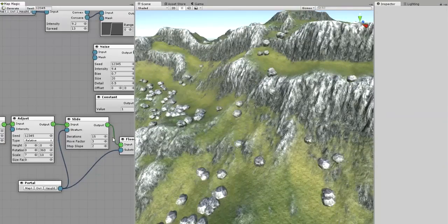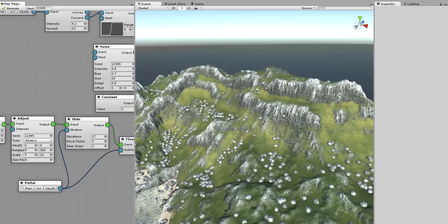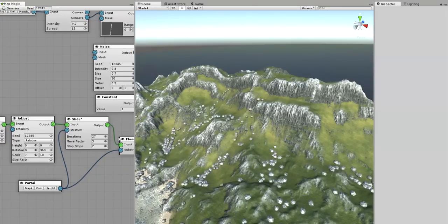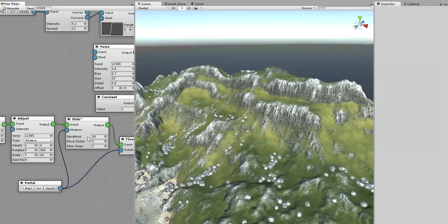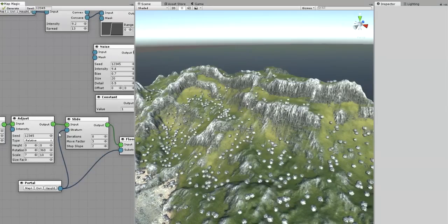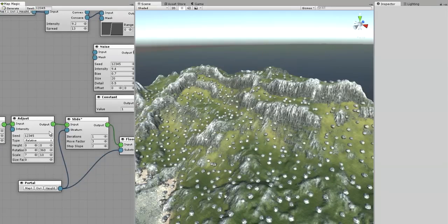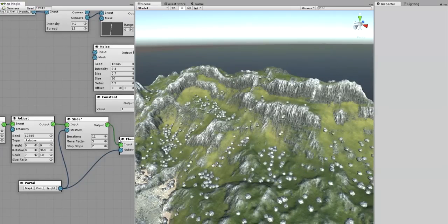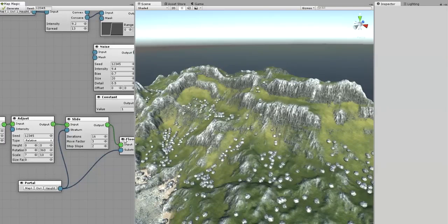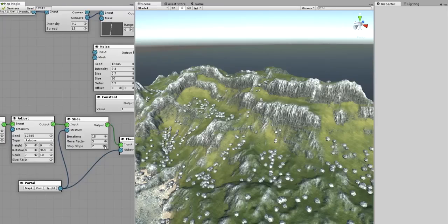Let me increase the number of the iterations and see the whole picture. You can see that the stones are sliding down to the ocean. They even form a stone torrent sometimes. But, to be honest, we do not need such a huge slide amount. We just have to remove the stones from the slopes. So we'll set the number of iterations to 10 or maybe 15. And then I will stop the stones from sliding down if they are lying at non-inclined land.